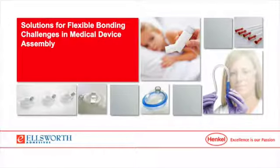So clearly that would be one red flag, because you may not get adhesion to especially some of these newer flexible substrates that are being introduced. But I'll give you an example from my history. We were working with a client who was doing a tubing assembly. They had done it with solvents for quite a while. Because of environmental issues and some of the things we've talked about with regards to materials changing, they evaluated one of the flexible solutions we reviewed today, the highly flexible CA or cyanoacrylate. In both a large and small diameter tubing assembly, we demonstrated to them about 2x the bond strength of the solvent.